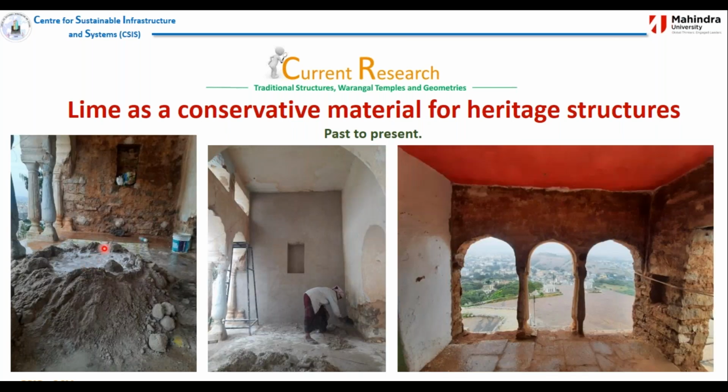And you can see this. We have fermented lime, which is mixed at the site, and then we have used it, and you can see the kind of finishing we were trying to get at that site. This was one wall we tested first, to see how good a finishing we'd get without any shrinkage cracks. So we left it for a month, then 2-3 months. Now this is almost 6 months. We have not found any crack on that.